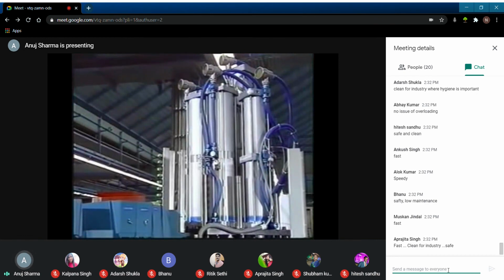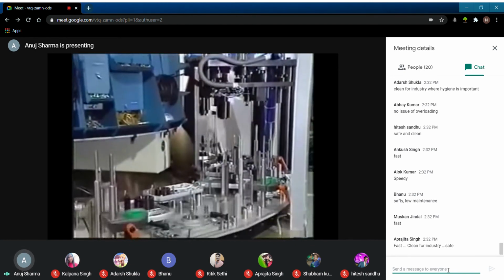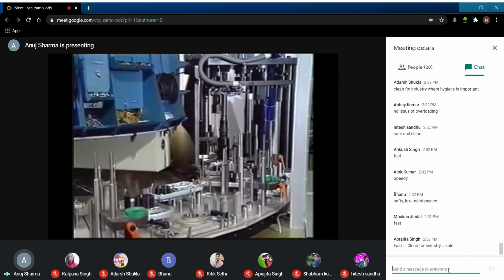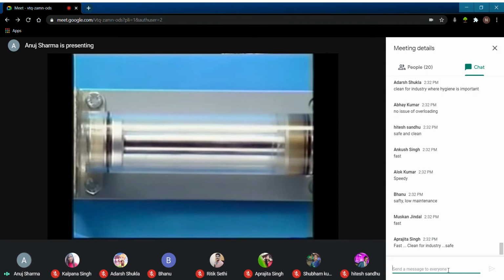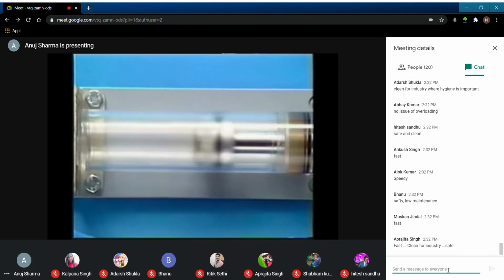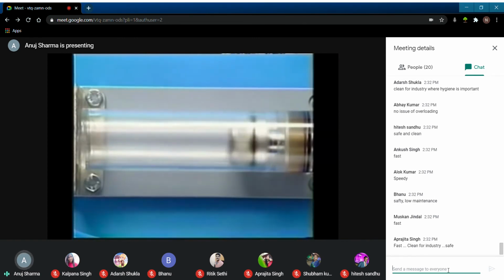Pneumatic cylinders are used to raise and lower manufacturing tools. This is an example of how pneumatic actuators convert energy in the form of compressed air to mechanical energy. To understand how they function, let's study a number of types of linear actuators. This is a transparent model of a cylinder. A linear cylinder is the most frequently used pneumatic actuator. Compressed air energy is converted inside the cylinder into linear motion.